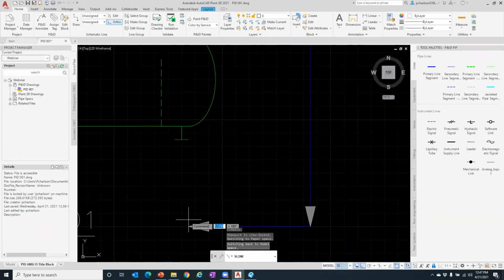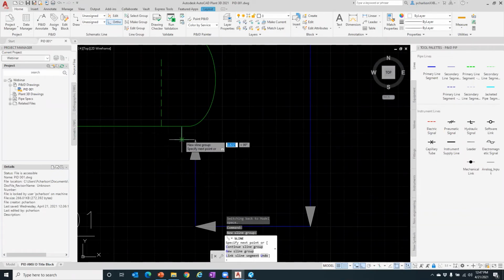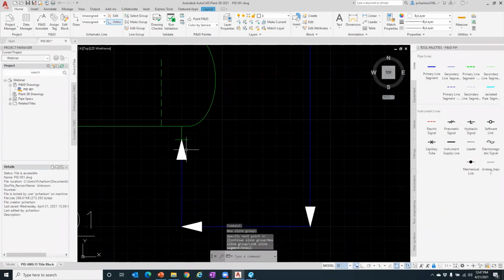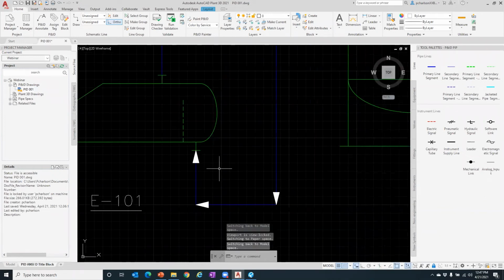Now, if you watch what I'm doing here, I'm going to start from here, and you think, okay, what happens if I go over here? It's going to be off target there. But if I go in and click on that node, you can see it automatically corrects itself. So in an AutoCAD instance, typically use the object tracking to line up those.